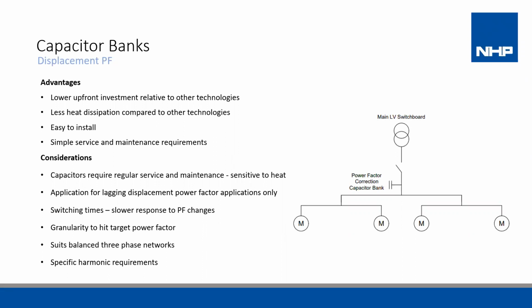Capacitors will only correct for lagging power factor. So if leading power factor in your site or system is of concern, then they will not be effective. The response time to hit the target power factor is a lot slower. In some cases, it might take minutes to actually reach the right level.